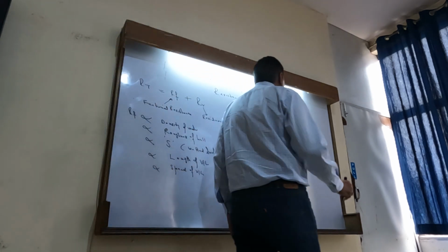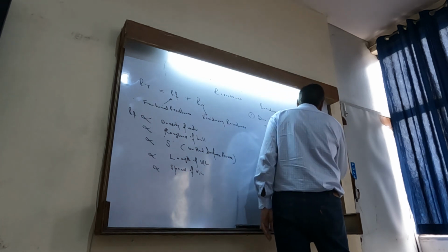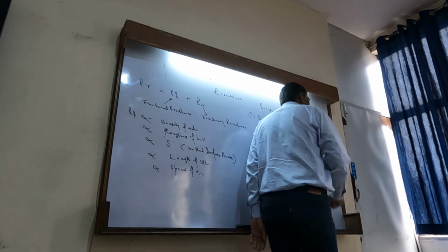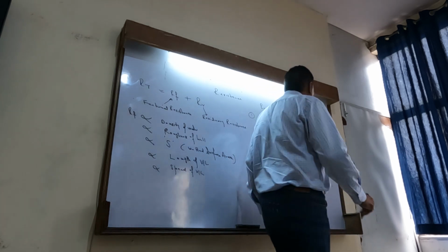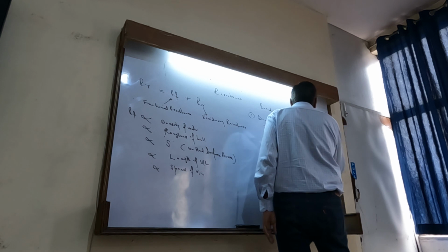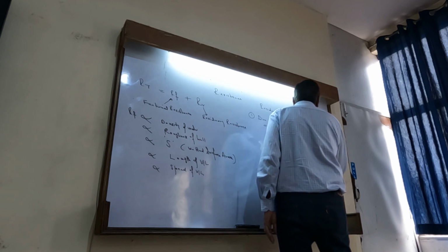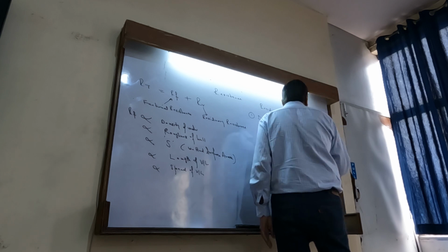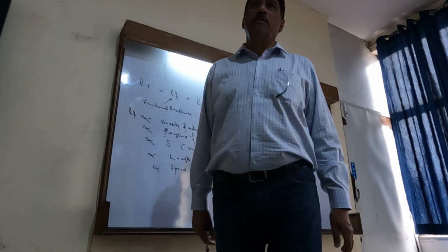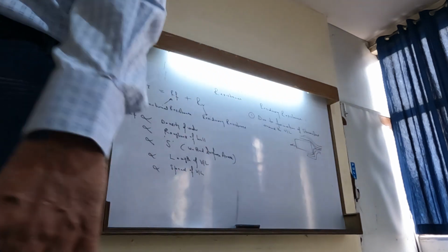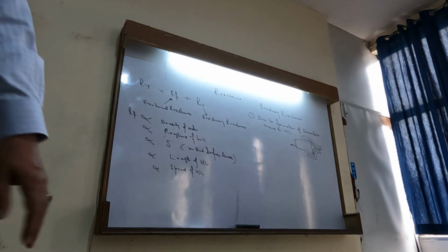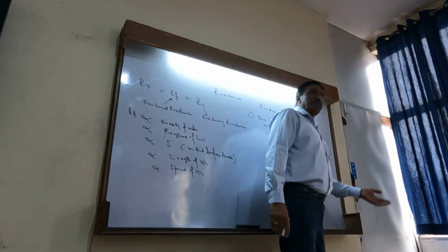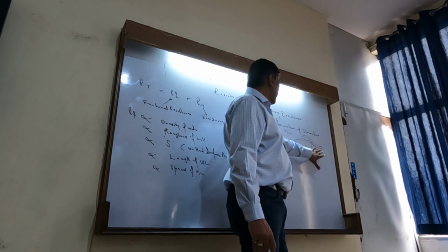Now let us see if the vessel is a barge. As the vessel moves, what will happen? These are the streamlines which will be formed around the vessel. The energy comes from the vessel only, because as I told you, we are not considering any external factors. So a barge, with a flat front, will have too much resistance because of the formation of these streamlines.